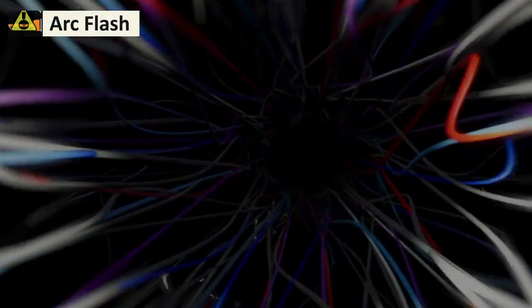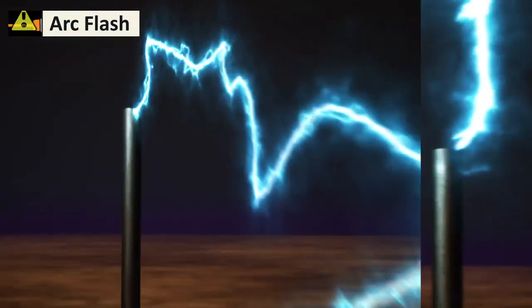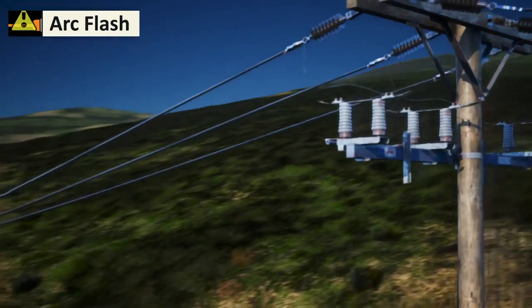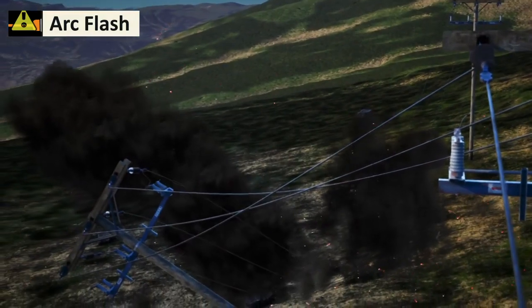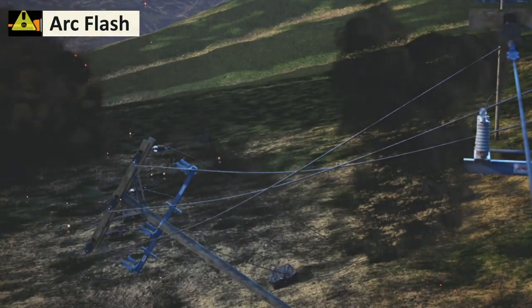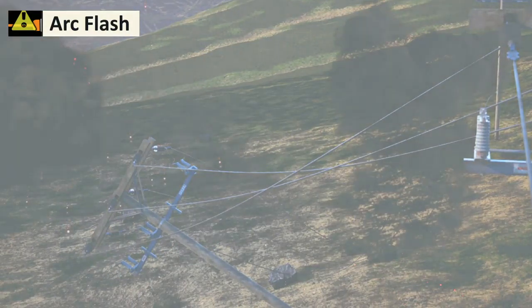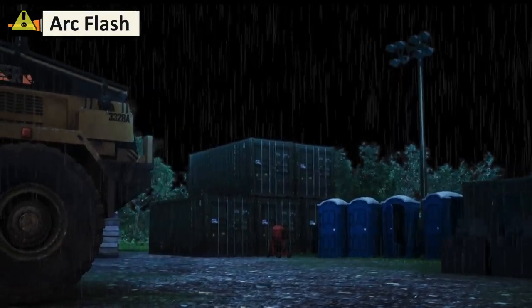Most forms of electrical faults are also capable of producing sparks or arcs. An electrical arc happens when a powerful electrical current creates a path through the air, either to ground or to another conductor. As the electricity flows through the air, it will create plasma, which gives off an explosive burst of light, heat, sound, and pressure, known collectively as an arc flash. Tiny, brief arc flashes are called sparks, but sustained arc flashes with more energy can be incredibly powerful and dangerous. Lightning is a familiar type of natural arc flash.